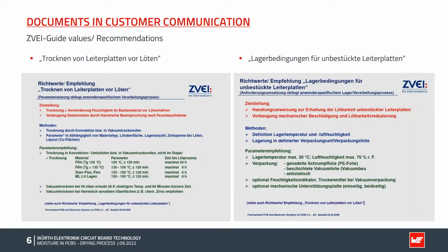It is important to note at this point that the fundamental necessity of drying before soldering must be considered as a necessary measure for all PCB technologies. Conversely, it means in particular that delamination during soldering after moisture absorption in your production is not a reason for a complaint, and that drying is a fundamental process component of the further processing of printed circuit boards. So that's important to know.